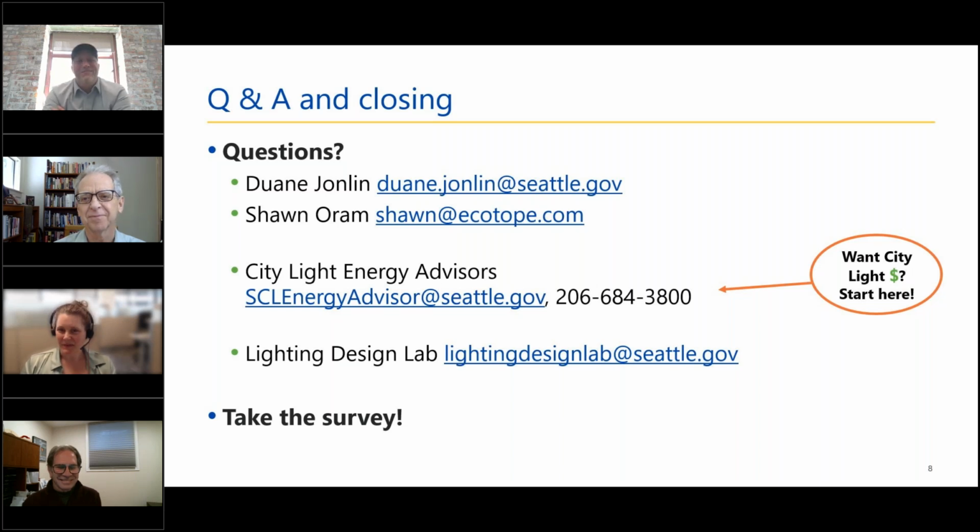Yeah. Okay, and Thomas asked, is CO2 single pass only? If so, how do you deal with the cold water being returned to the primary tank when in defrost? Oh, good question. When a system is in defrost, it actually stops pumping, so it's not going to destroy your precious hot water. It just turns off. So in 1 hour, you run for 10 minutes, you turn off for 5 to melt ice.